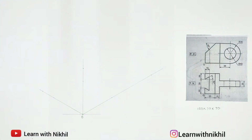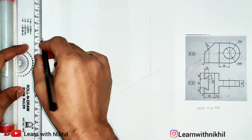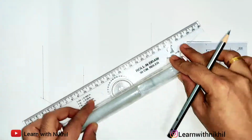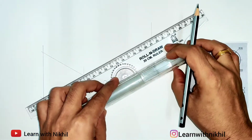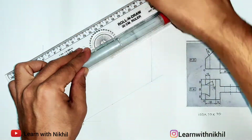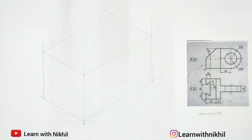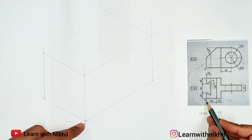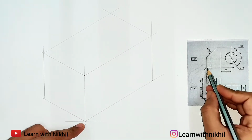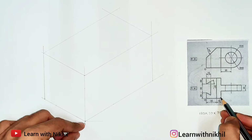Now using these three dimensions we will draw a rectangular box. Draw the lines parallel properly. While drawing, do check whether we have drawn the parallel lines properly and we have got the dimensions properly. Now starting from the point O, as you can see, we have a total distance of 50 millimeter, that is 35 plus 15. We have a dark line.